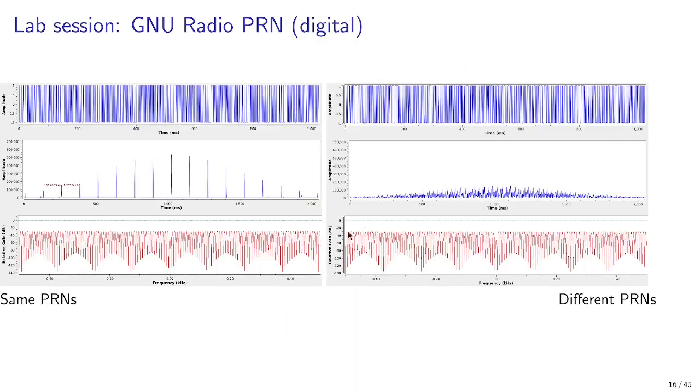As can be seen, the spectrum of the GLFSR of maximum length is flat, since there is no repeating pattern. And again, if we correlate with the right pattern, we do get correlation peaks every 120 samples, and no correlation if we run the code through the wrong sequence.